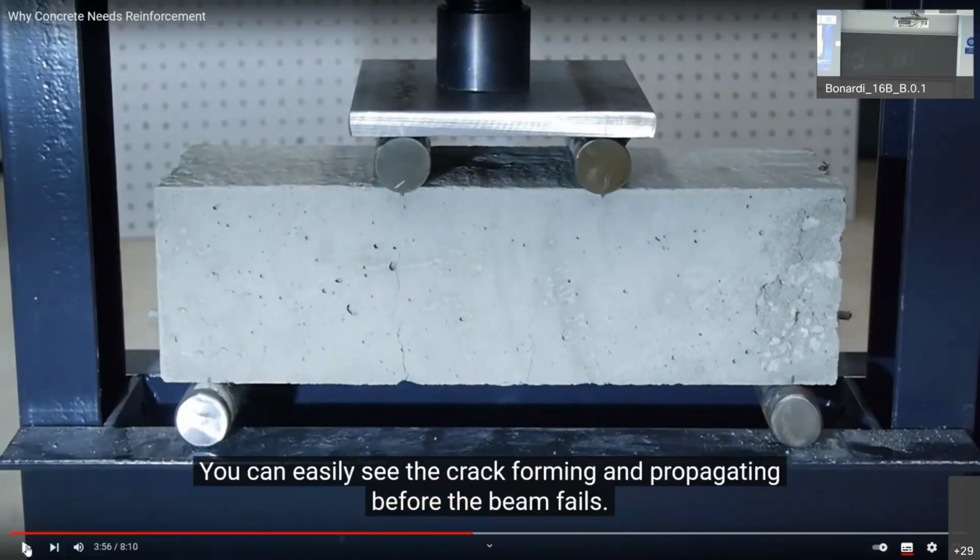And that's the perfect representation of what I showed you before. Here we can imagine, in the upper part of the cross-section, for example, the neutral axis that reaches this point, or maybe this point. I cannot see if this is a crack, but we can think about this. The neutral axis so far is at this depth from the top of the cross-section.